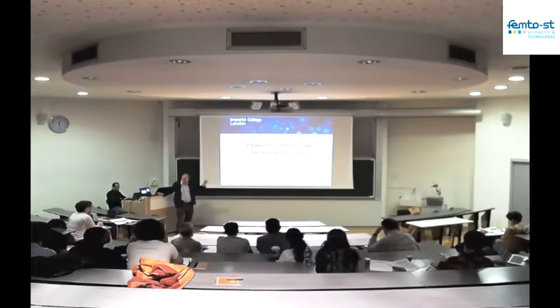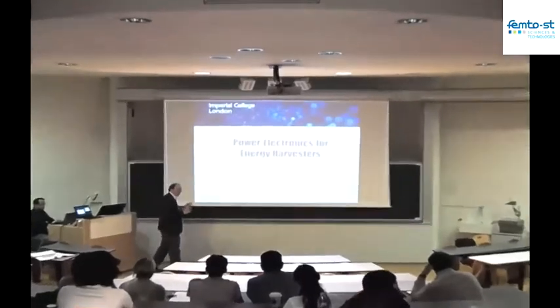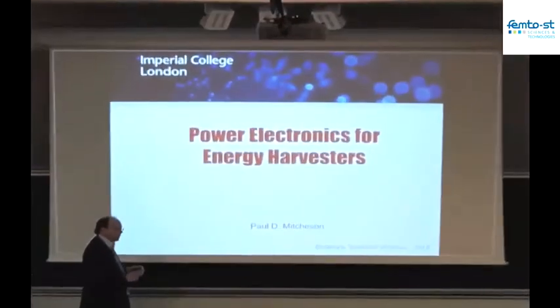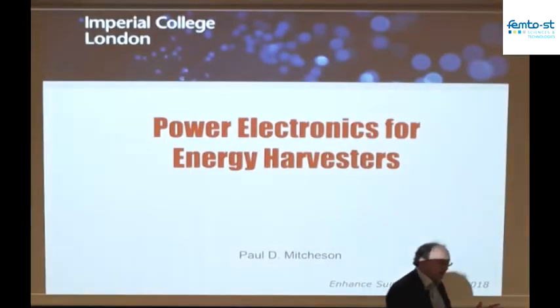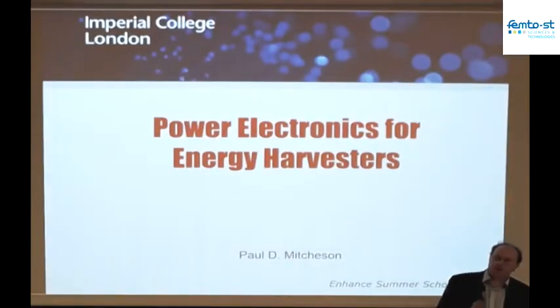Now we've had a very brief overview of some of the aspects of power electronics there for the different types of harvester, and I hope that what you've really gained from that is the understanding, at least at the moment, that in order for the harvester to operate and get the maximum power generation possible within its mechanical domain, what I've got to do is set up the harvester's mechanics properly, and a big part of that is setting up the right force on the transducer. If I've got the optimal force on the transducer, I'll maximize the power that I can generate into my electrical system.